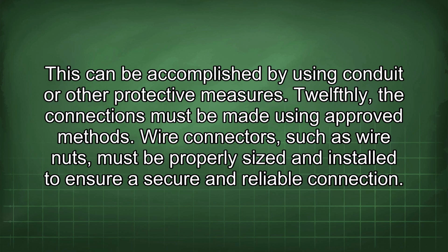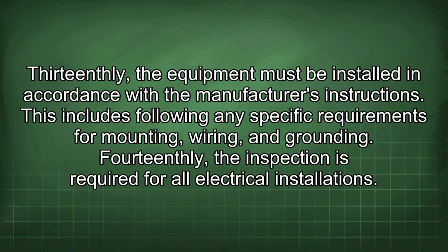12thly, the connections must be made using approved methods. Wire connectors, such as wire nuts, must be properly sized and installed to ensure secure and reliable connection. 13thly, the equipment must be installed in accordance with the manufacturer's instructions. This includes following any specific requirements for mounting, wiring, and grounding.